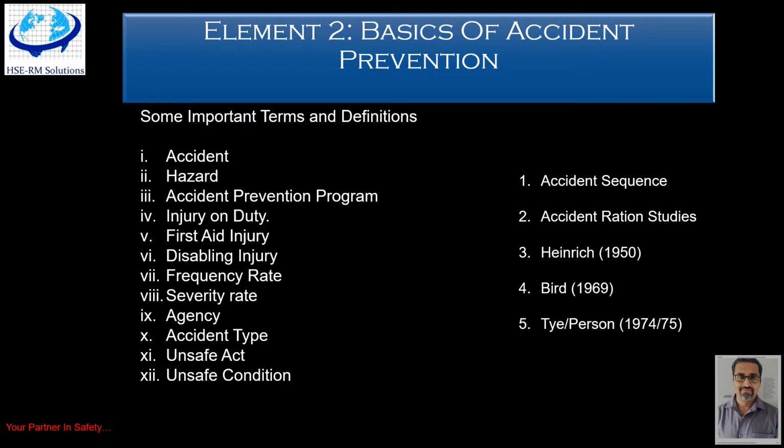Any condition that may result in the occurrence of or contribute to the severity of an accident is a hazard. Suppose a belt and pulley drive is not guarded and it is running. If someone's finger is caught in that belt, then the finger may not only get injured, but it may be amputated, thereby increasing the severity of the accident.